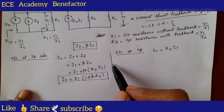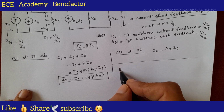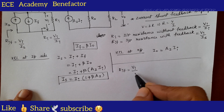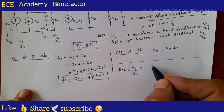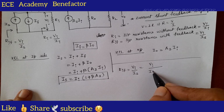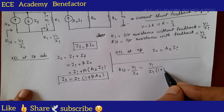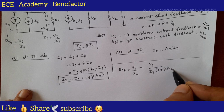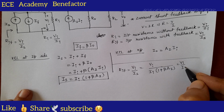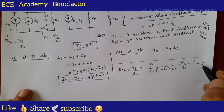What is the definition of RIF? RIF is equal to VI by IS. Substituting this IS here, it is VI by II times 1 plus beta AI. And what is the ratio of VI by II? It is RI.